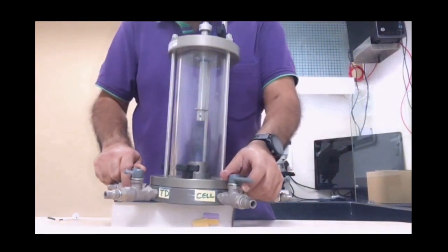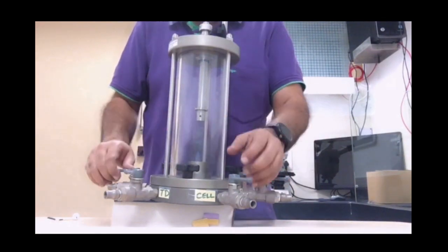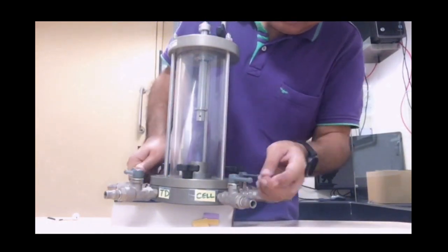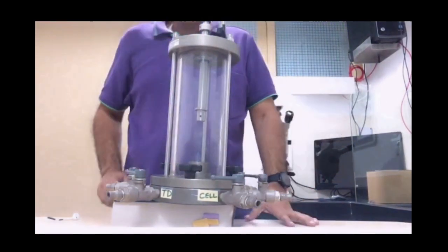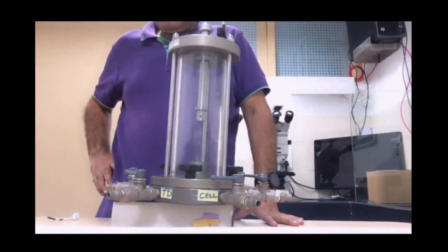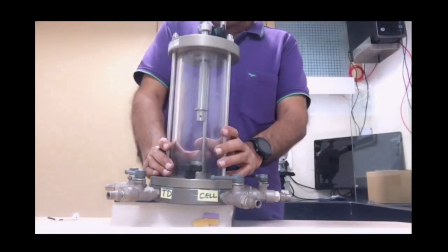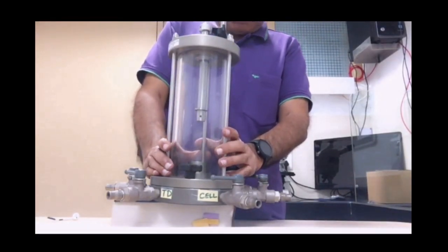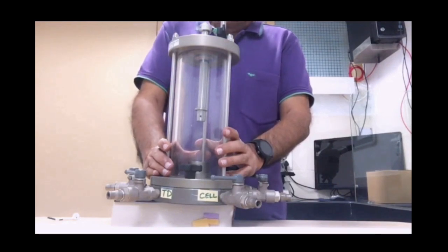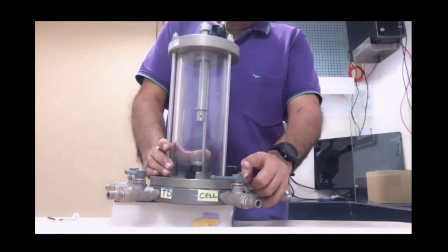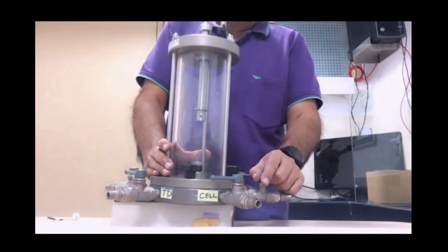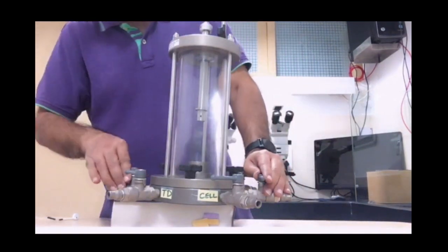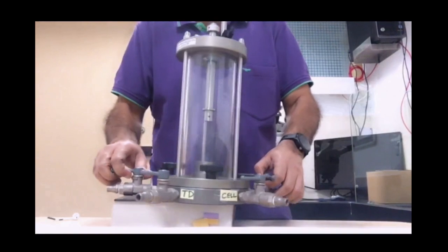So once the sample has stabilized to a new back pressure and cell pressure value, I would close this back pressure, close the cell pressure, and then jack it up. We have just seen that the pore pressure we increased is now at 190. The cell pressure is at 200, and I need to check my B coefficient again. So all my valves are closed except for the PPT valve, which is open. It just gives me a reading.